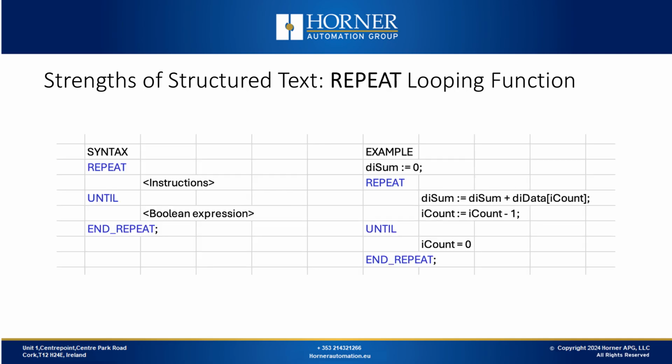The third looping function in structured text is the repeat function. This function will repeat its instructions until something is true. Similar to the while function, the repeat function should also be coded with a condition to avoid infinite looping.